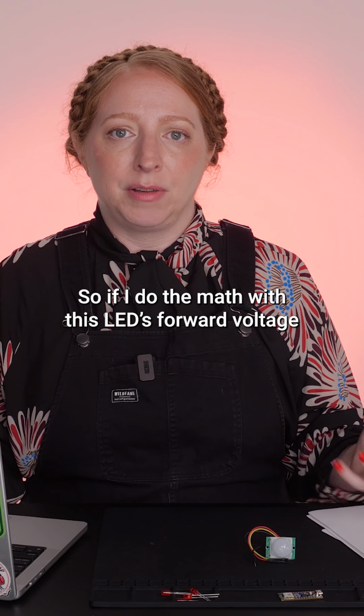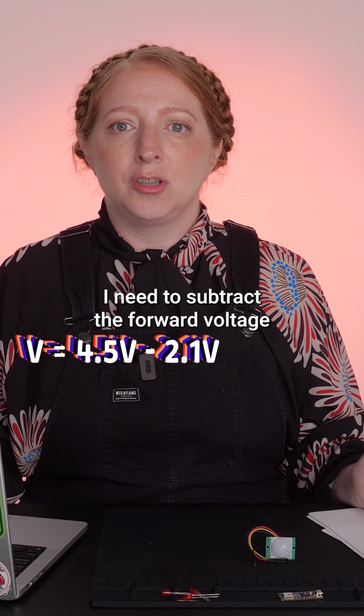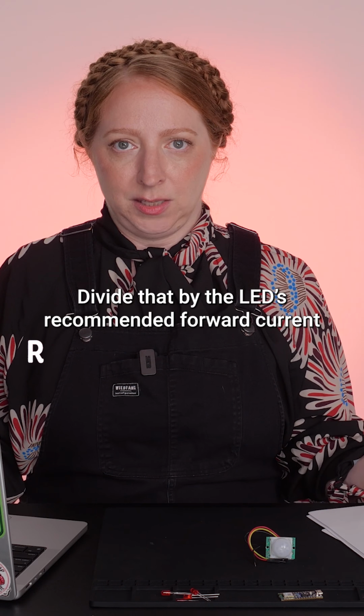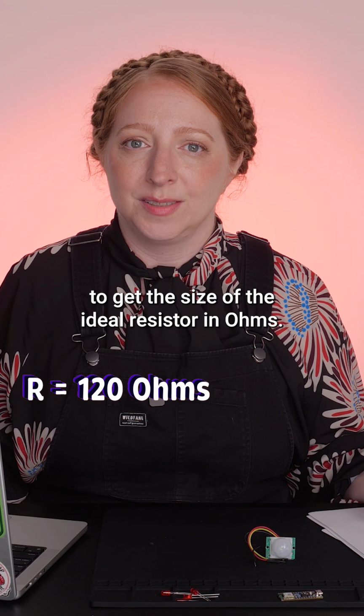So if I do the math with this LED's forward voltage and this 4.5 volt battery pack, I need to subtract the forward voltage from the supply voltage to get V in my Ohm's law equation. Divide that by the LED's recommended forward current to get the size of the ideal resistor in ohms.